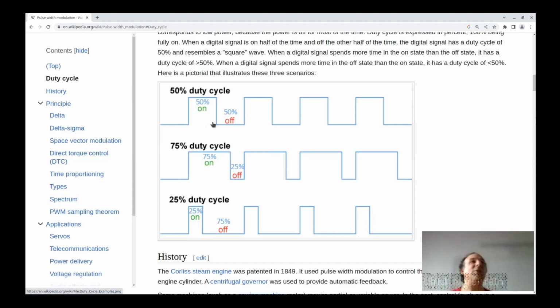These are the 2 values you can play with when we work with PWM, and you can use that to dim LEDs, to control motors, and it's a way to do something analog on a digital port. The funny thing is, if you use the Arduino IDE, you do an analog write to a digital port. It uses the word analog in there. It's very confusing to write something analog to a digital port, but that means we are using PWM.